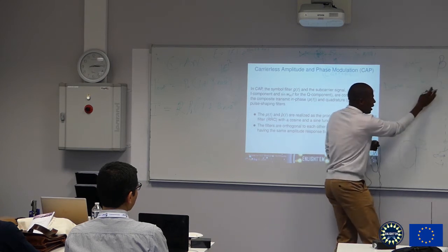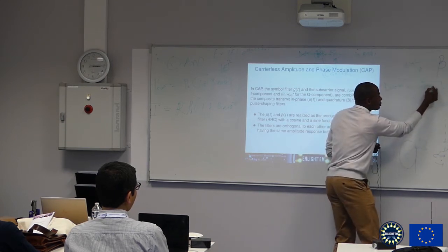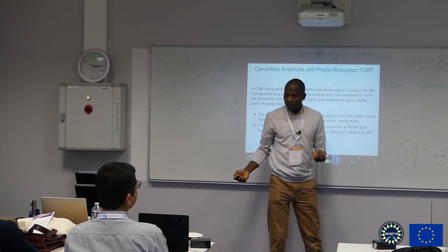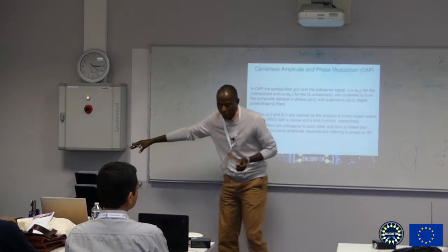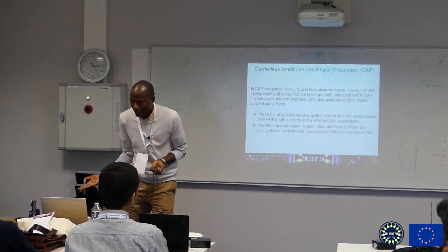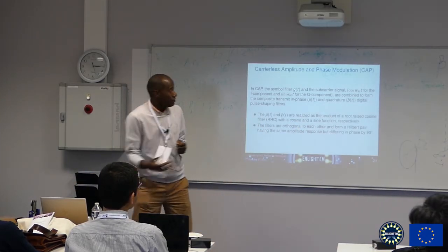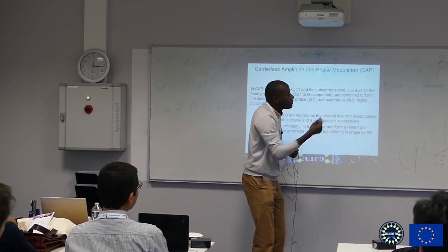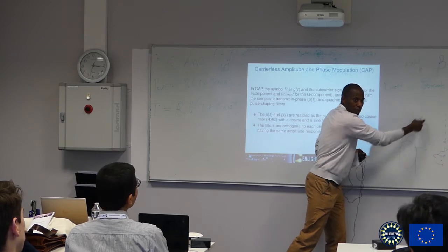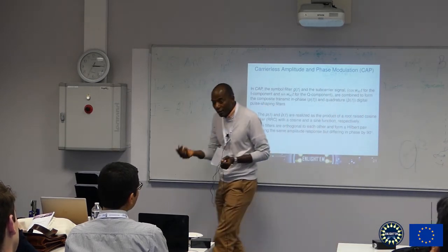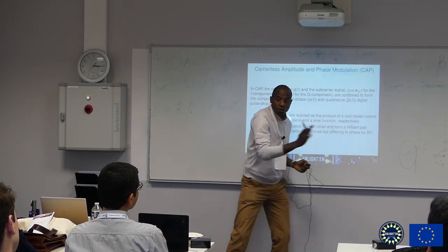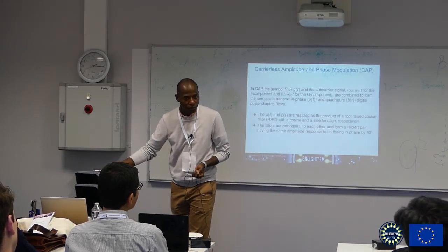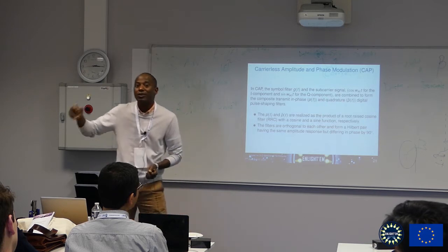Here is now GT times the carrier frequency. Do you understand? I just multiply them as a separate block. It's essentially the same thing. Instead of doing them separately, I combine these two together first, and then I put my data to it. Why do we do that? Because we believe that because the carrier frequency is so low, it's in baseband, we can use FIR filters. So if you design them as a filter, it's a lot easier.